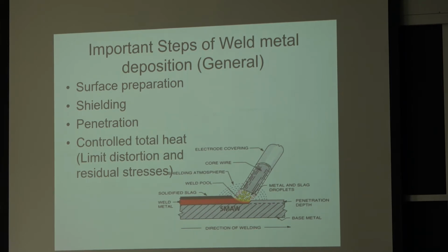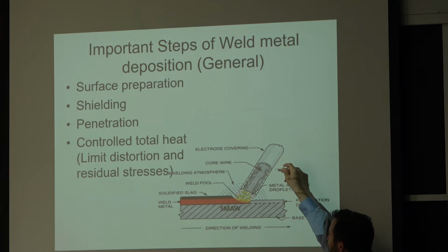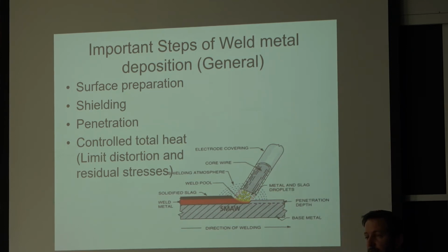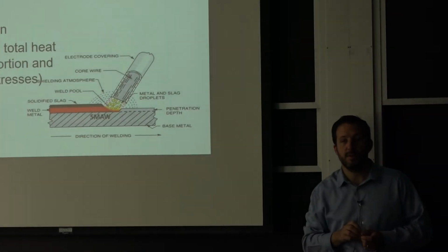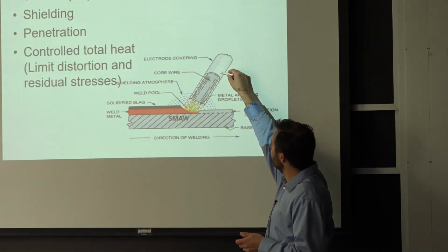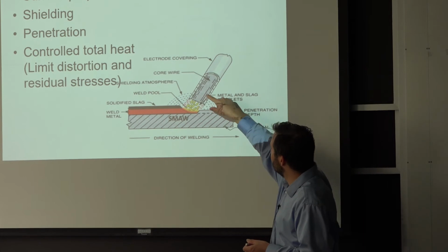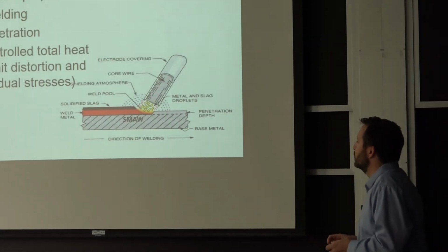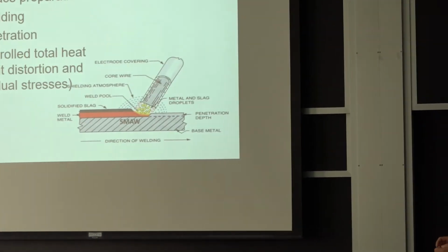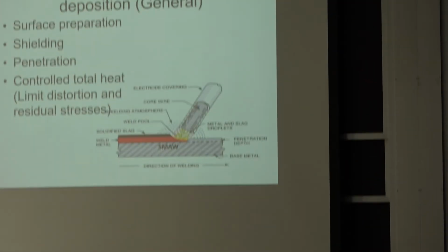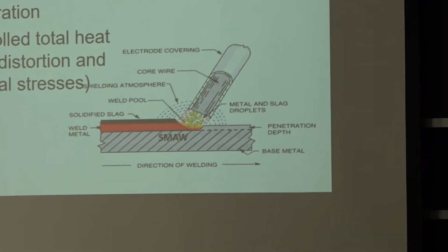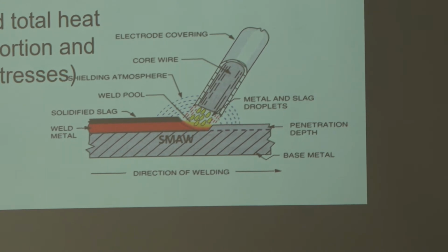So, melted steel, whoa, it will want to oxidize. So what it means is in this case, and there are other cases we'll go over, it's a very important part of welding to protect that melted steel so it doesn't oxidize and become extremely brittle. So in this case here, it's essentially a little bit of a slurry that is over the metal electrode, and those shielded electrodes need to be kept dry a lot of times if it's a good quality electrode, so you don't have the moisture starting to come in when it engages with the liquid steel.